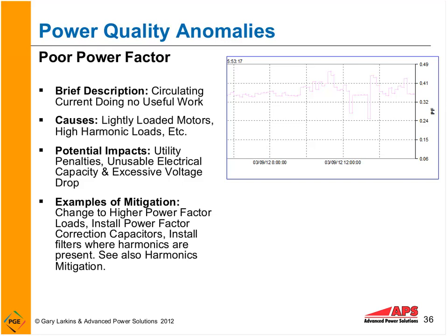So impacts, of course, utility penalties. We may be losing capacity. We may see excessive voltage drop. A lot of times folks are looking to go put power factor correction capacitors in. We'll talk about that, because when you have harmonics, and we'll talk about what harmonics are in a little bit, with adjustable speed drives and electronic loads, you have to be very careful about putting power factor correction in.